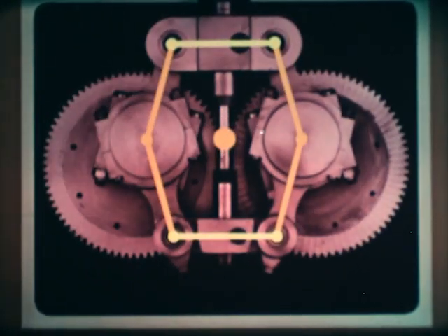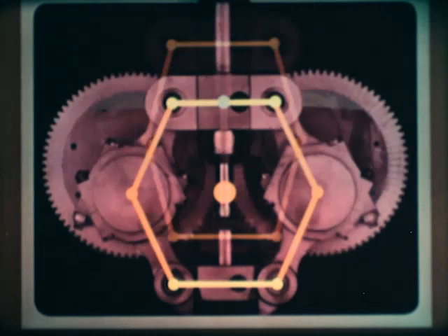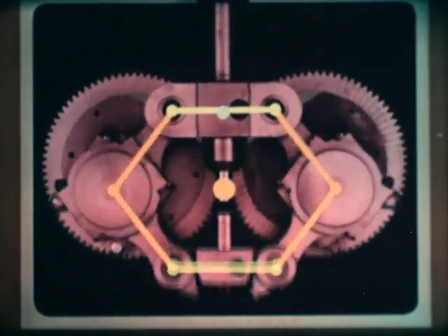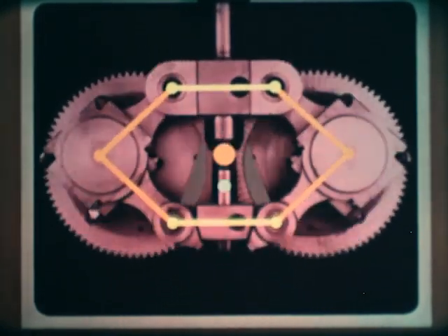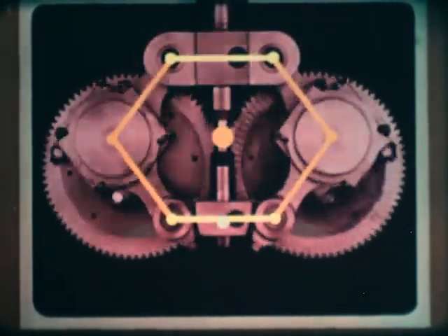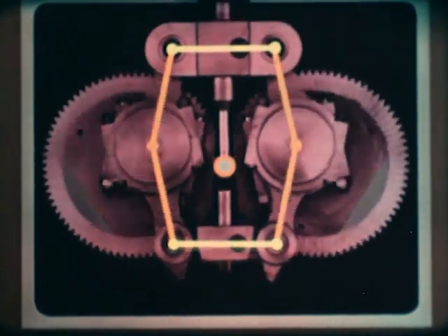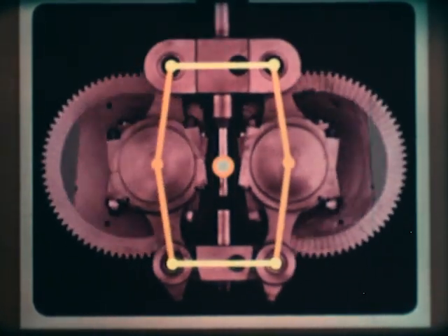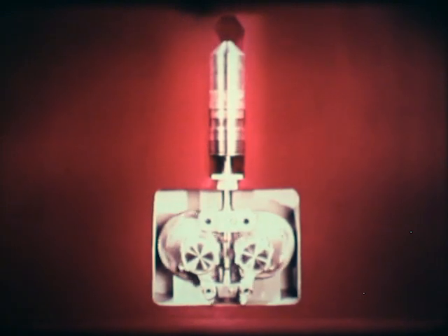The inertia forces which result can be compensated by two identical counterweights, whose combined center of gravity is in counter-movement to the center of gravity of the rhombus. The masses of these counterweights can be evaluated so that the center of gravity of the whole system remains static. This means that this single-cylinder hot gas engine is inherently balanced. Perfect balance means complete absence of vibration at any speed.